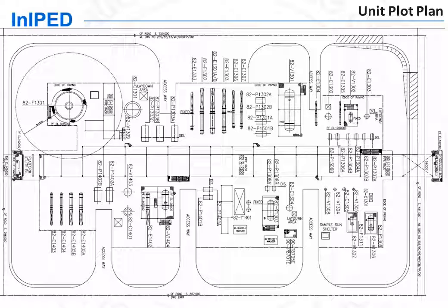Fixing the position of equipment is a major step in the design. To do this, the involvement of the plant owner, the future operator, is necessary. Therefore, a review of the plot plan is organized with the plant owner. This review is done in 3D and is called the first or 30% model review.